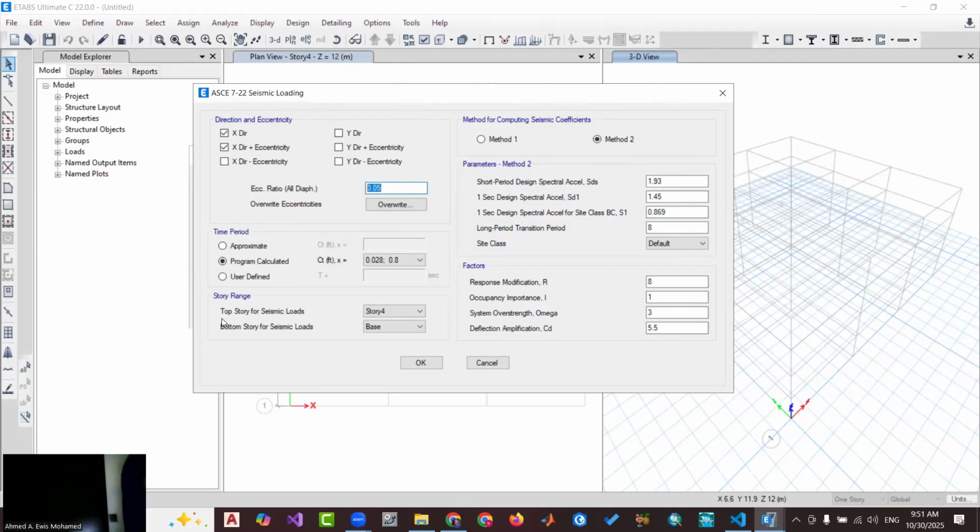Why is this? Because we can say, yeah, center of mass is in the middle, but we don't confirm this, because maybe some people, for example, as a live load, stay here, and here there are no people or no furniture or nothing. So we can't say 100% the center of mass is in the middle, for example. It depends only on the slab and weight of the column, because live load may change from here to here.